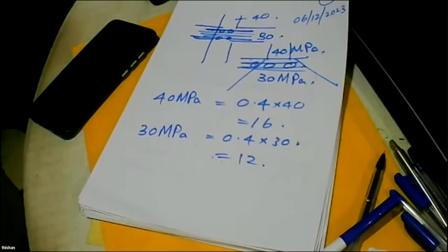These days we are doing a project where, what is the general capacity of a 1,200 pile? 6,000 kilonewtons. What is the general capacity of a 1,500 pile? 10,500 kilonewtons. But in this particular project, our 1,200 piles of 40 megapascal will carry 11,000 kilonewtons, nearly twice, and our 1,500 millimeter piles will carry 17,000 kilonewtons, all with 40 megapascal concrete for the pile, with 0.7% maximum reinforcement in the pile.